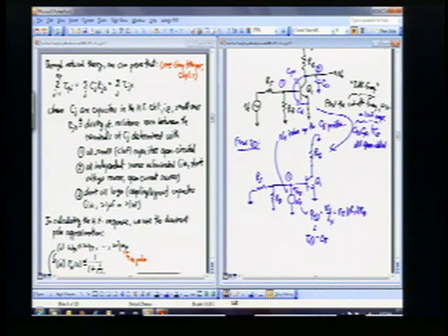So that's the capacitance in shunt with node 1. So C1 in your inspection formula is C-pi. So now I can write tau 1 equals C-pi times R pi parallel with RS parallel with RB. That's my first time constant right there.